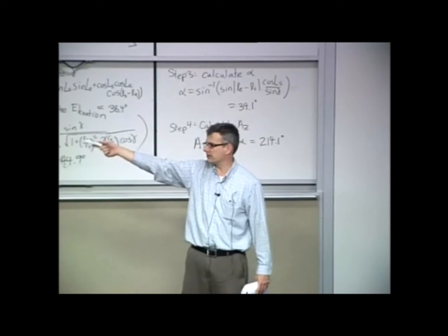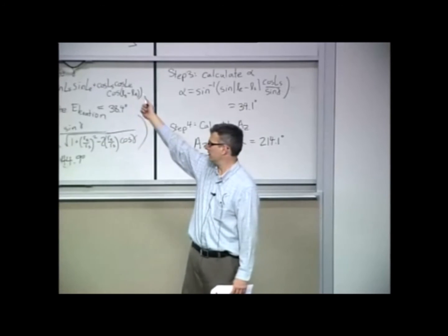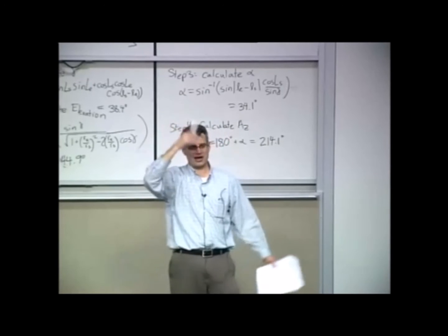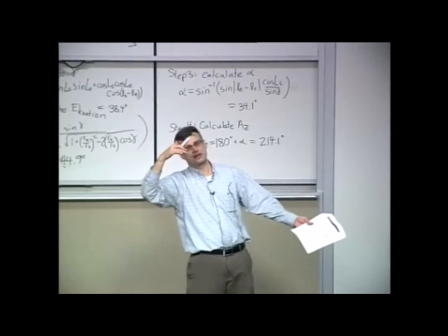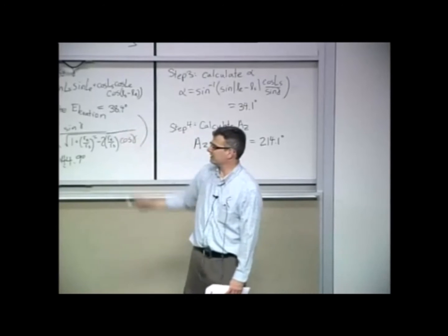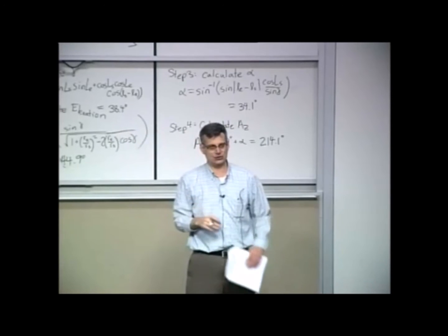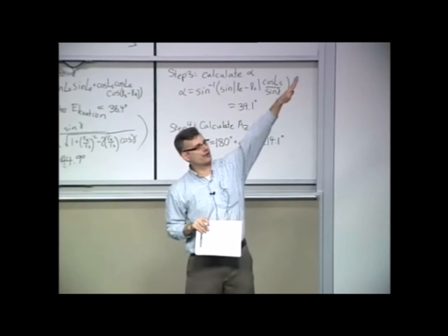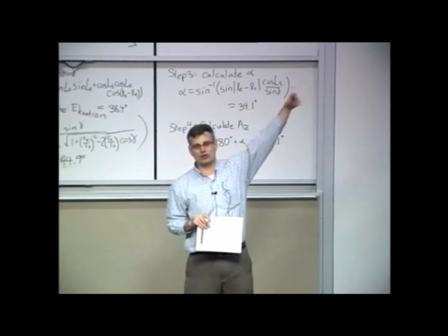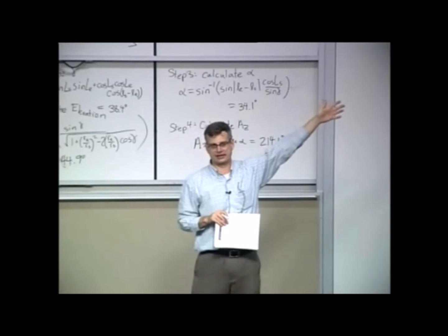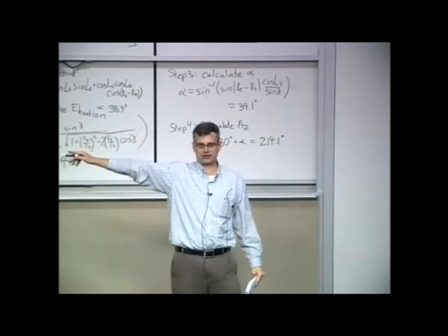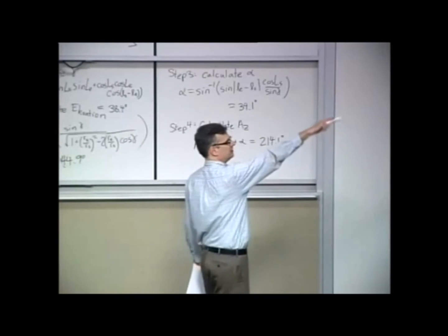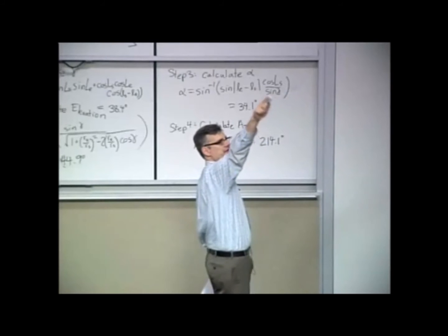So that means north, west, east. If we just kind of visualize it in our mind, we're up on the Earth at about 34 degrees latitude, and the geostationary Earth orbit satellite is kind of shot out from the equator multiple radii of the Earth away. And so if that's north and that's south, I figure I'd have to raise my dish up here and then tilt it over there somewhere.